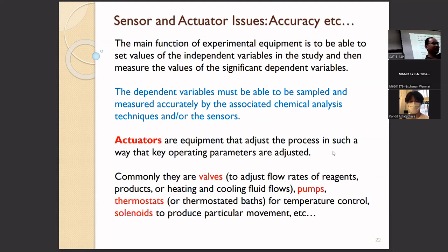You have some vapor of alcohol. If the vapor is very high, higher than the limit, the pressure of the gas in the system will rise. If the gas in the system is higher than the limit, the safety valve will automatically open to release the gas from the system. This is very important for engineers.